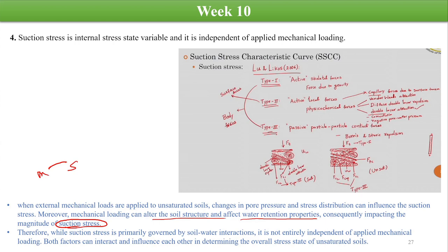So mostly it is said that the suction stress is primarily governed by the soil water interaction, but it is not entirely independent of applied mechanical loading. So this statement that suction stress is an internal stress variable independent of applied mechanical loading may not be truly correct.